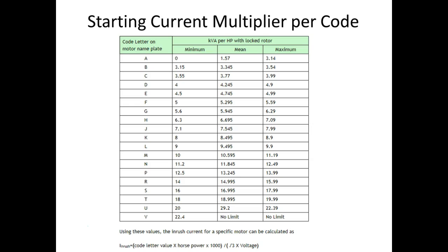That's when we start under load, not when we're going to do it, because we're going to run these motors unloaded, right? If I was to start that thing under load, it could pull up to what? We use a rule of thumb of 6 to 8, but it actually varies depending on the code of the motor. Everybody understand that?